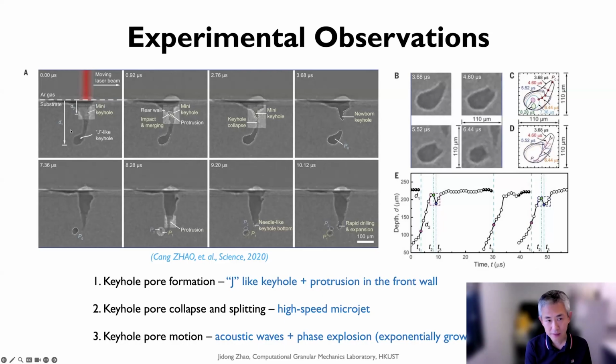First it forms the so-called J-leg, the letter J, and it looks like a letter J here, forming a J-leg keyhole. Okay, and as I mentioned, the keyhole is typically a depression full of high-speed vapor, so it's quite dynamic, it's not stable. So at the bottom part it can bulge bigger, but at this part it can generate a so-called collapsing of the two surrounding walls.